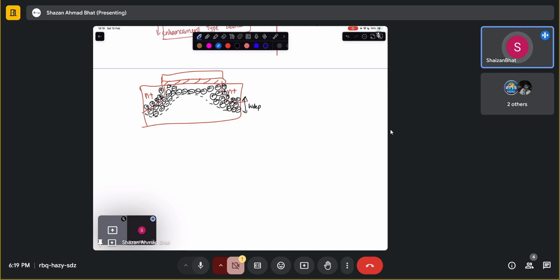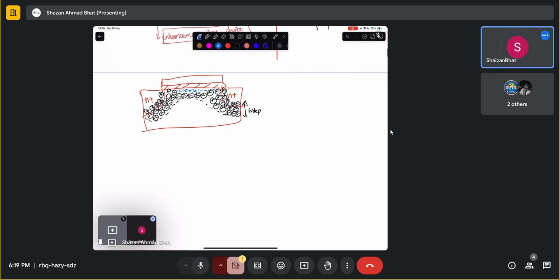And then apart from it, there are electrons which are induced by the gate in the channel. So you see that it's quite a messed up situation in between here. There are depletion charges, and there are also free electrons. You can change this scenario by applying different gate voltages and different drain voltages. You can change it altogether, because if you apply, let's say, a positive voltage here and ground this totally, then what is this diode getting? N plus is connected to the positive, and negative is connected to the P. That means it's reverse biased.